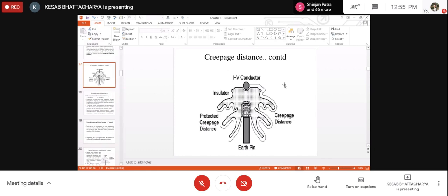And if a short circuit path develops through the body of the insulating material, that short circuit path will remain, and whenever you want to operate that insulator, direct or conduction current will flow through that short circuit path, and the purpose of providing the insulating material is totally lost, and there will be a dead short circuit between the line and earth path.